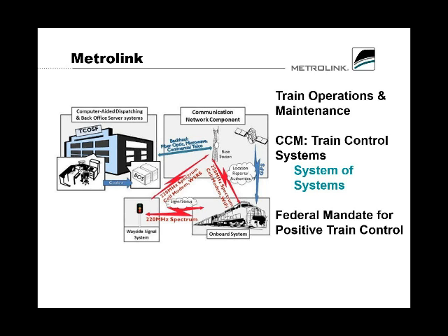It monitors the speed of a locomotive, and in the event an engineer or the locomotive is expected or predicted to be faster than an upcoming speed restriction, or may not stop in time for an upcoming stop target, the positive train control system will take over the train and apply the brakes. So that's the system that we're talking about.